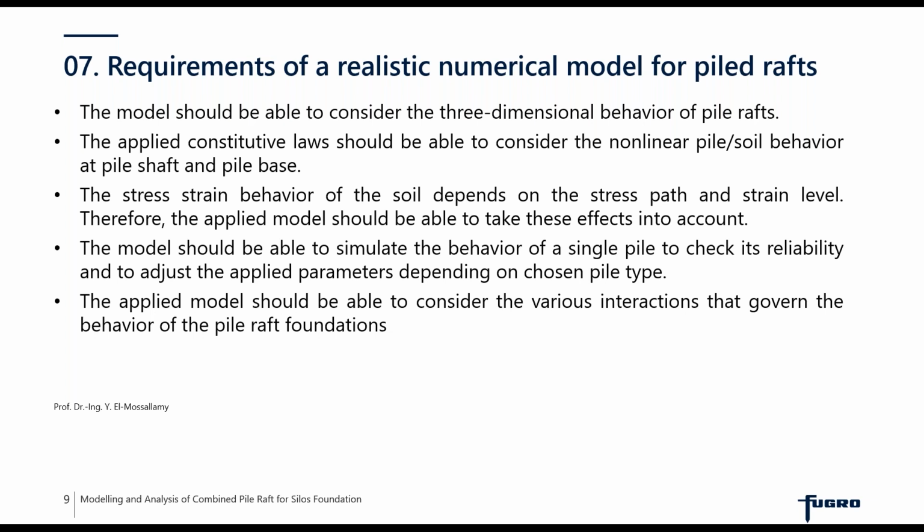Now, the constitutive law should be able to consider the nonlinear pile-soil behavior at the pile shaft and at the pile base level. The material model which you are utilizing for modeling the soil and rock should be able to consider the stress-strain behavior of the soil, which we know is dependent on the stress as well as the strain level.